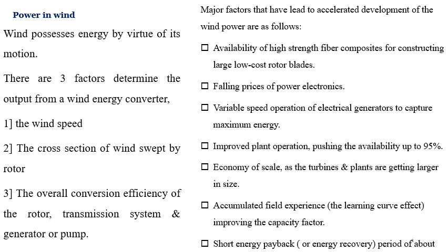Well designed blades will typically extract 70% of the theoretical maximum, but there are losses incurred in the gearbox, transmission system and generator or pump. Including all these losses, the overall wind turbine efficiency could decrease to about 35%, and the remainder is loss.